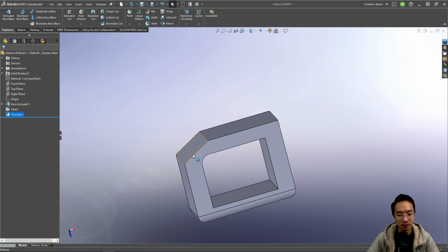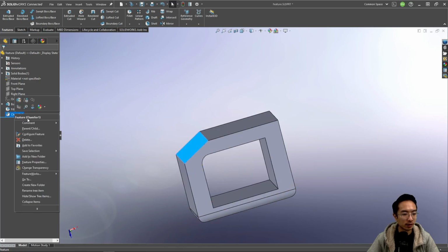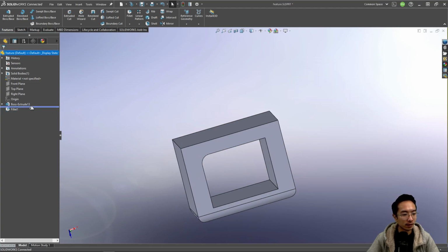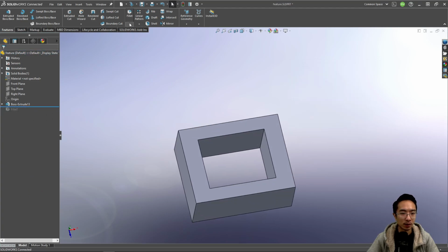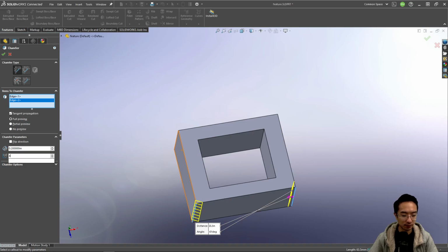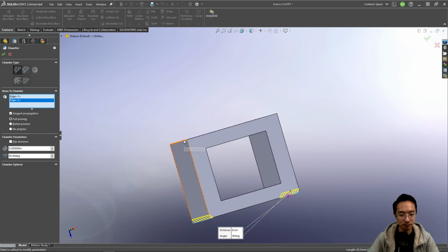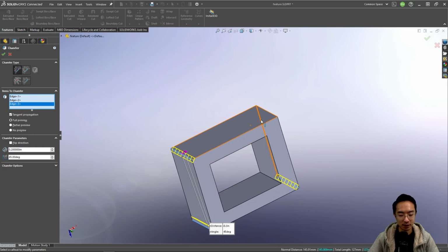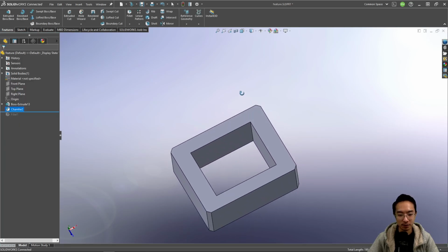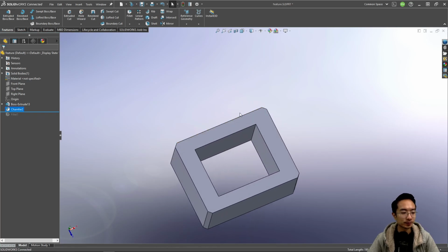In practice, you probably won't make one this big. So I'm going to delete this. And let's say we didn't have these fillets. Maybe in practice you might do something like chamfer and then have a small one like 0.2. Then you could go around each corner. I'm going to change this back to 45 degrees. So in each corner you could have a little chamfer if necessary, and it'll just make your part nice and round. Okay.